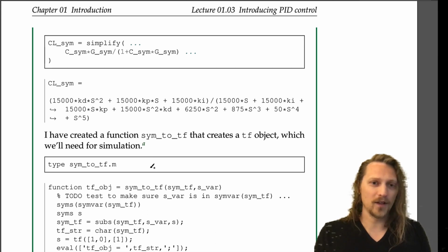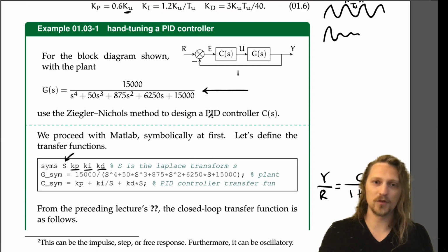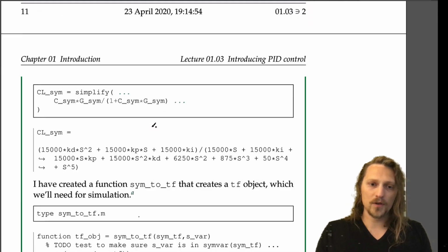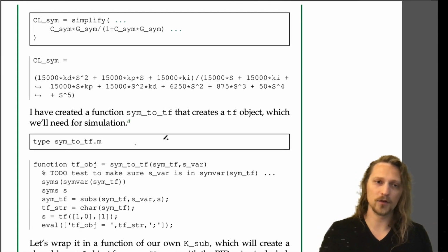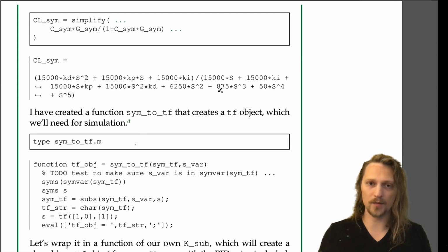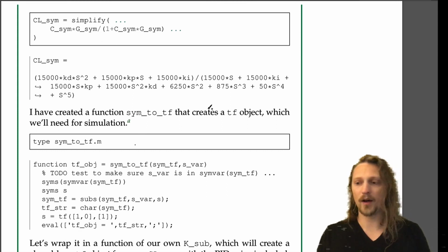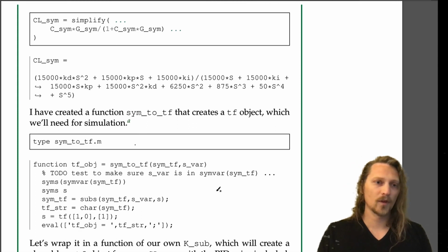we can control. So now we have a system that has a plant, which we presumably can't control the position of these poles, for instance. It doesn't have any zeros in it. But once we put in the PID controller, we have control of all of these different terms in the closed loop transfer function. So we can affect how the output responds to different commands.